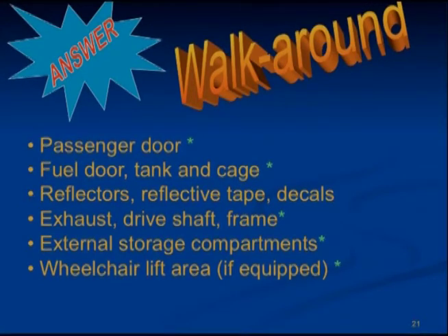Check underneath the bus on the door side. Sight check the exhaust system for sagging exhaust pipes, tailpipe, or muffler. Look for visible exhaust or soot. Make sure that the frame is not damaged and nothing unusual is attached to or under the bus. Make sure the drive shaft couplings are secure and free of foreign objects. Make sure that the U-hangers are secure.